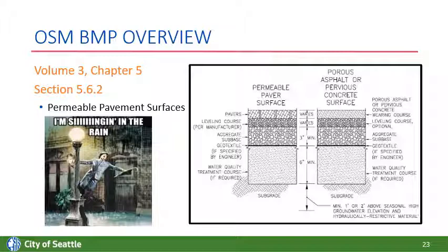That's really to make sure that if you're going to have a permeable pavement surface, the underdrain is located such that the equivalent amount of aggregate is still below that underdrain, so that effectively the permeable pavement surface still acts as a permeable pavement surface even though it's being underdrained. And a note has been added regarding the additional aggregate depth for stormwater storage below the underdrain.